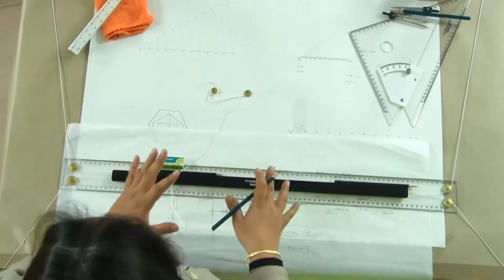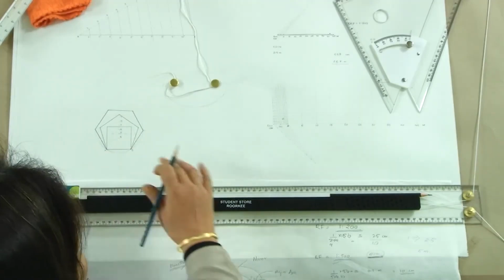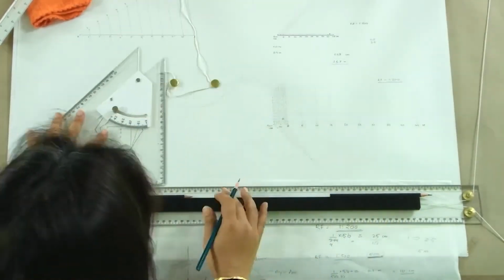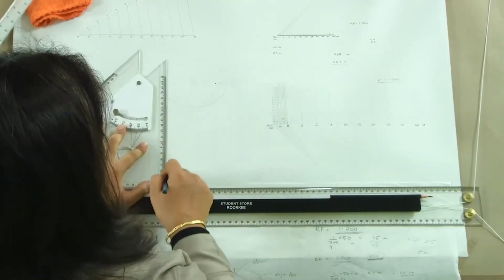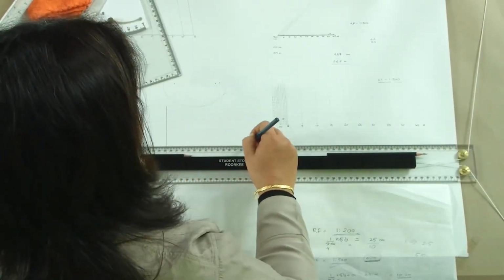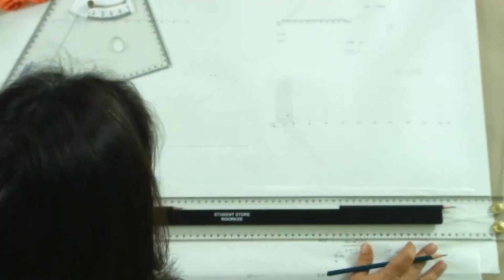However, we often do not draw using this method in engineering drawing, in engineering graphics, and what we need to do is we need to know the directrix, the distance of focus, the eccentricity, and we will draw using that method. Now, if we have to draw using directrix, what we have here is a directrix which is given. We will draw an axis of the ellipse perpendicular to it at any point. It is not fixed. These are just generators.